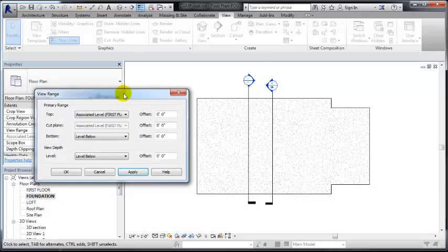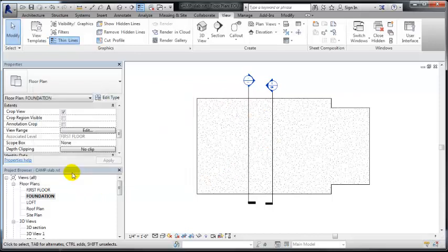This is an example of what that slab would look like. If we were just looking straight down on the slab, we wouldn't really be able to see the haunch. But what I'm going to be doing is showing those hidden lines in this top view. And we can do that by actually turning off our floor region. So we'll hit OK. This is correct so far. So I'm going to hit OK. And then I want this floor to actually be turned off in this view.